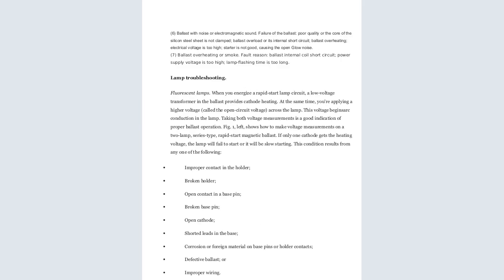The ballast with noise, sometimes it is noisy or makes a magnetic sound. Then the problem is the failure of the ballast. There is poor quality, or the core silicon steel sheet is not clamped, or maybe the ballast is overloaded or its internal short circuit causes ballast overheating. The voltage is too high and the starter is not good, causing noise. Another thing is ballast overheating or smoke. The reason is that the ballast internal coil must be short-circuited, or the power supply voltage is too high.